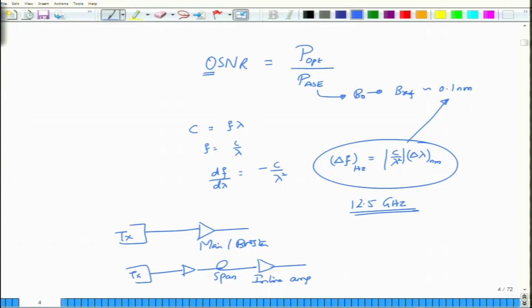Okay, so, this is also something that is possible, and at the receiver, just before the signal comes in from the fiber, after the last mile of the fiber, just before you take the signal into the receiver, you have one more amplifier which is called the pre-amplifier. Of course, at all these points you may have to, or indeed you will have to, put appropriate filters so that you are limiting the amount of noise that comes into the band of the signal of interest. So, this is about erbium doped fiber amplifiers, and we will stop here.